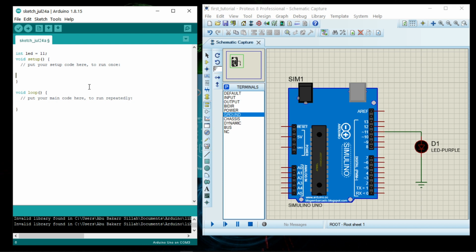So here let us come to our void setup. In our void setup, let us put pinMode. That's supposed to be a capital M. In mode, you see it's turned red. Is this red in fact, or orange? Okay, let's say red. You see the color changes. That means that the IDE is happy and it recognizes what we've said. Okay, pinMode, put a bracket.